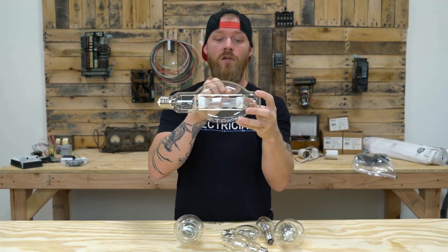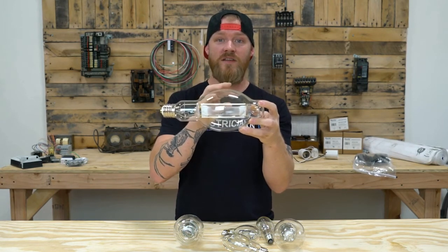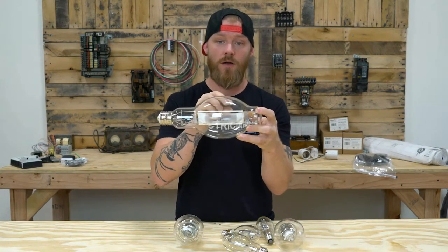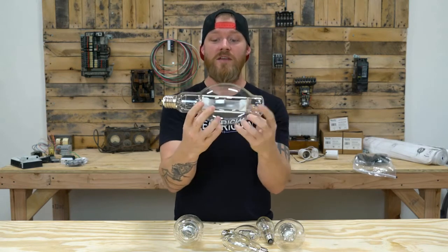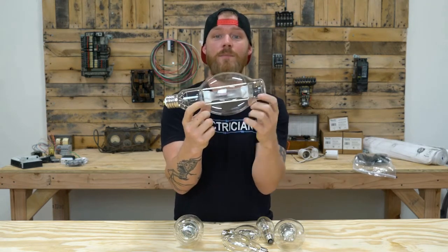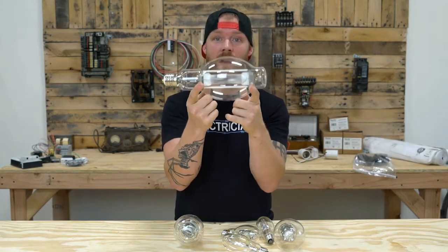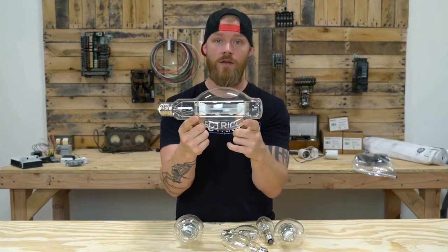About 25% of the heat that comes off of this lamp goes back into the lamp to maintain the temperature of the arc. 75% of it is wasted as heat, but another 25%, when you paint the white, is reflected back into the tube, so that amount of heat is able to stay in the tube and stabilize the color of that arc without it shifting on you.